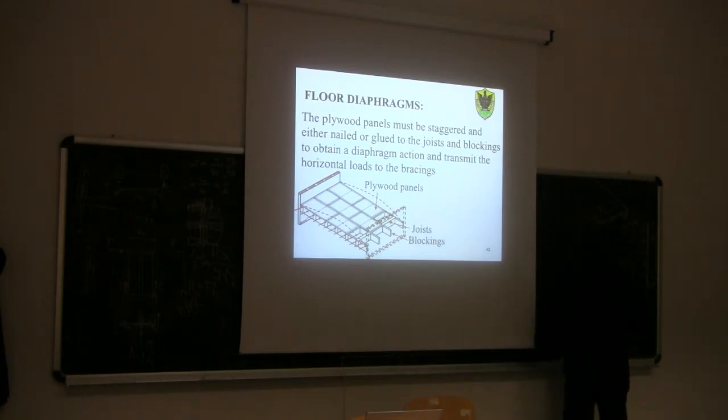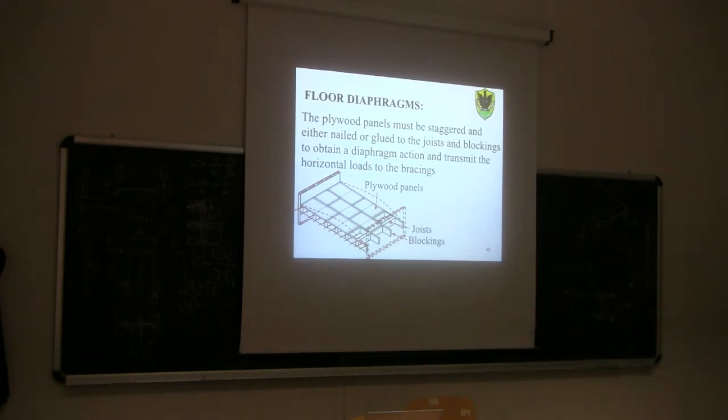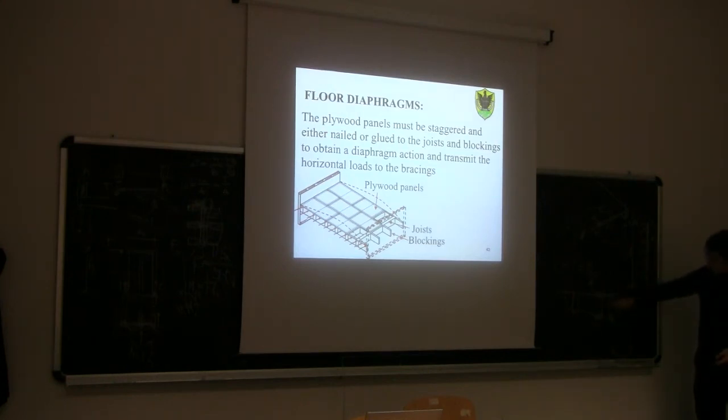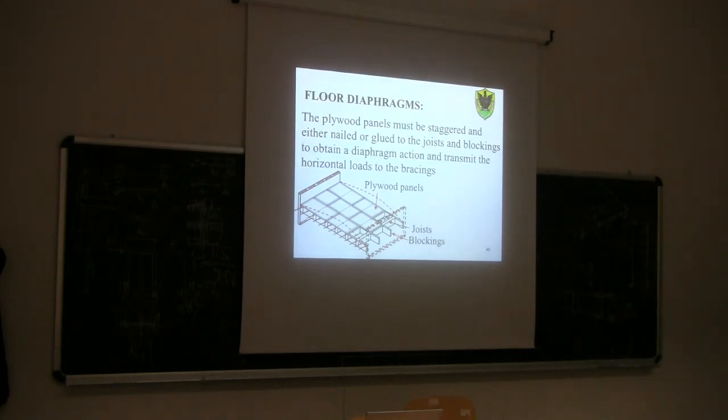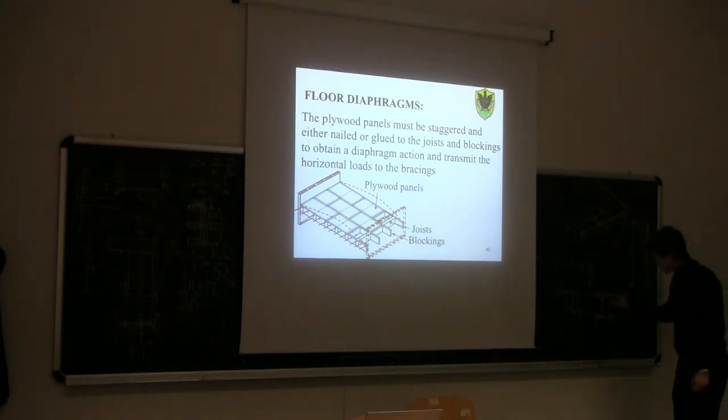So basically the axial force is transferred through here and here, through this metal strap, and you just pass laterally above the joist. You don't go inside the joist because the joist otherwise is subjected to tension perpendicular to the grain. So again, it's better to leave the joist outside this kind of mechanism. Of course, the problem is that in tension this works, but we need to make it work also in compression. Compression, this is loaded perpendicular to the grain in compression.